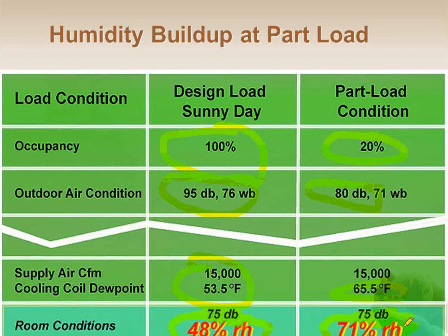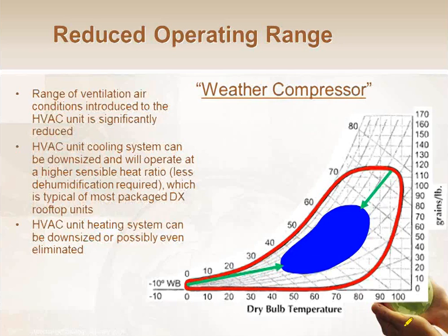So most of your DX systems, unless they have modulating compressors, they're going to have this problem where it's hard for me to control humidity when it's not a design day. The ERV is going to help me with that substantially.